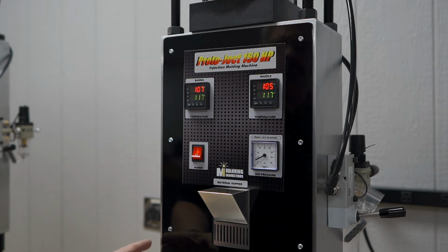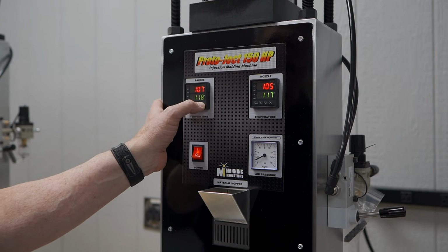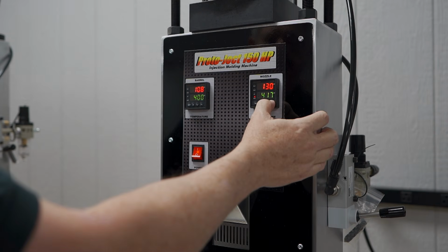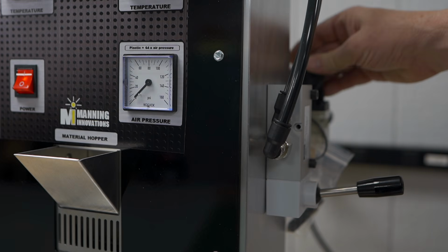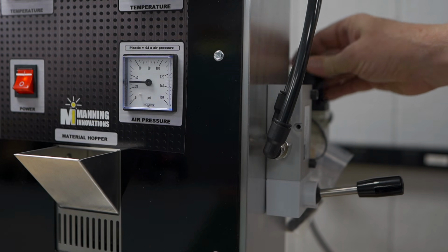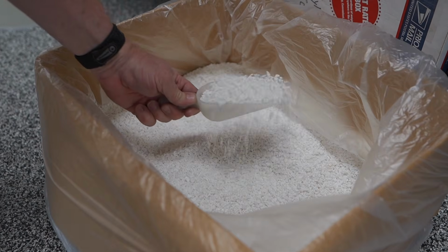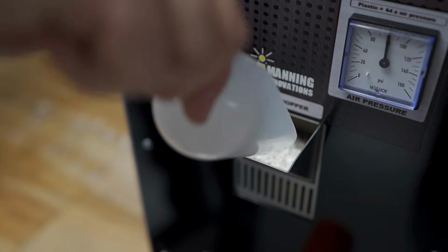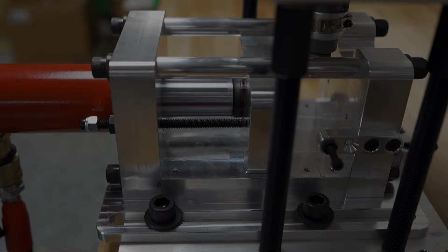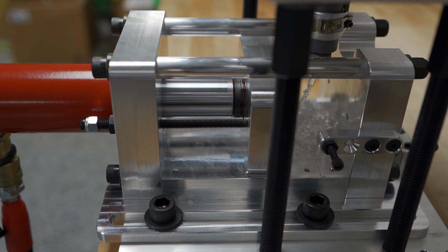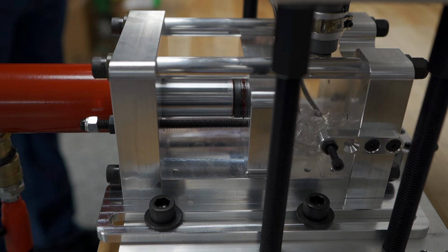Startup of the machine is similar to mine. You turn on the power. He has 2 heat bands and therefore 2 controllers, so he can set them separately. Then setting the initial injection pressure. On his machines you can fill it with quite a bit of plastic and don't have to worry about keeping the plastic below the top of the cylinder. So unlike my machines which have a valve, he can just purge it right away without having a purge block underneath.